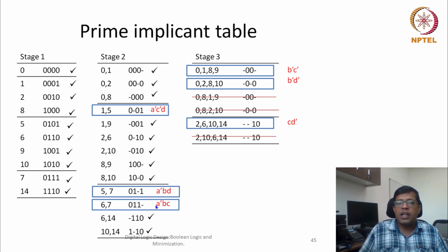The second thing is because the comparison can be written nicely in terms of an algorithm, this could also form a nice optimization. So this optimization can be written using a systematic algorithm in any of the high level languages like C, C++, Java, etc. So after finishing this prime implicant table, now we find out which prime implicant should be included in our final solution.